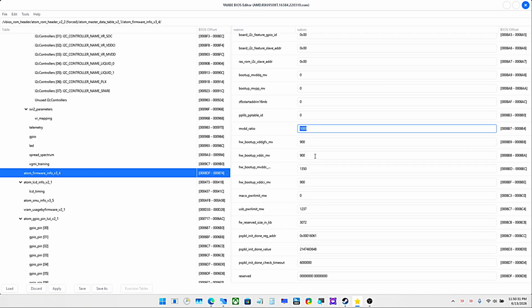If we set it to 0, we can run ultra low voltage at idle, all the way down to as low as 900 millivolts, rather than 1000 millivolts, which is what the stock is. So that's pretty sweet. We can run it down to 900 at idle. I think you might be able to run it down below that even. I think actually you can run below that.